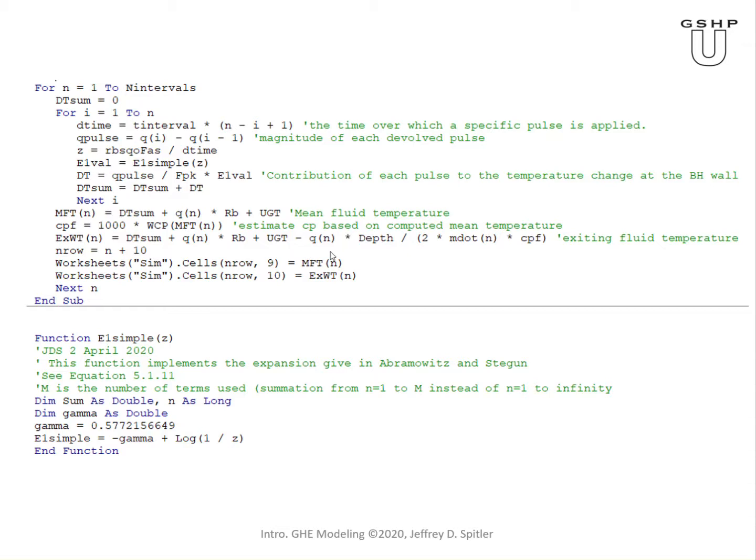Here our Q is, we computed to watts per meter already, so we need to get it back to the total watts. So we multiply by the depth, or I think in the equation I called this L, QL. Okay, and then we write this back to the spreadsheet. Okay, so that's what it looks like. Let's actually pull it up and bring it over here.